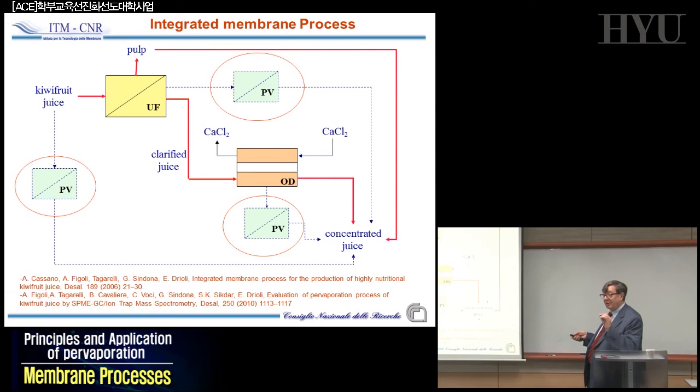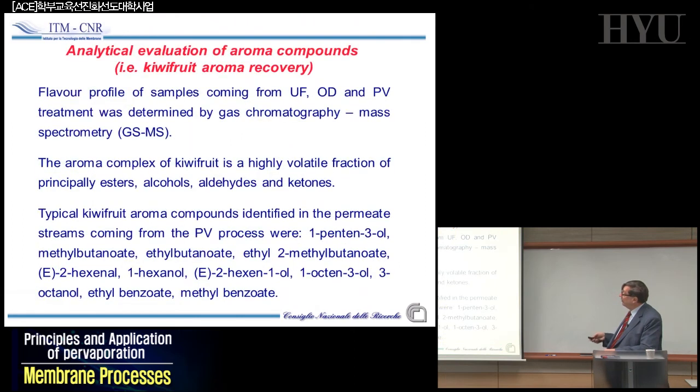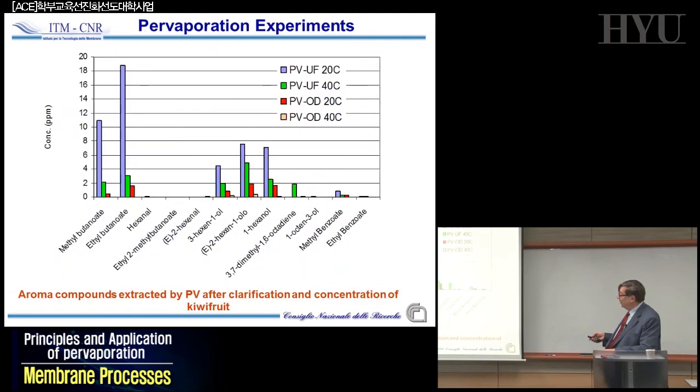So you can have exactly the same Cabernet Sauvignon, the same Chardonnay, etc., and that's what was real life for them. And you can separate here, and you can re-add after the concentration. That is, you enter with 18, 20 brix, and you go out with 65, 70 brix at the end. So pervaporation can be utilized for solving this problem. And what's important, if you do this, you can separate.